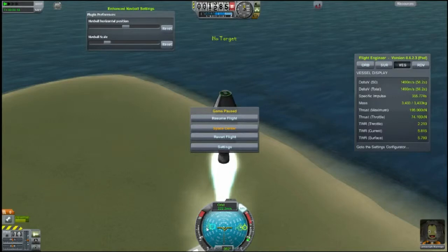These are ghosted velocity and anti-velocity indicators. You can barely see the anti-velocity one since it's over on the other side, but it's basically indicating the direction that you have to turn to reach the velocity indicator. This also comes into play when you're setting up maneuvers. Say you're setting up a maneuver to go that way. The maneuver indicator will be right here. The ghosted maneuver indicator will be right here, telling you that you need to go around this axis to get to your maneuver indicator without having to spin around and hunt for it.